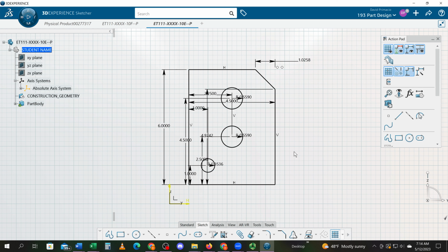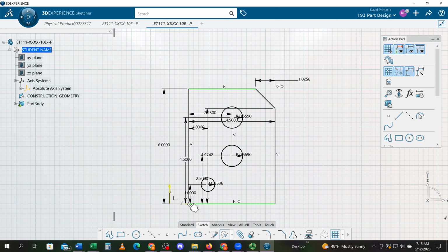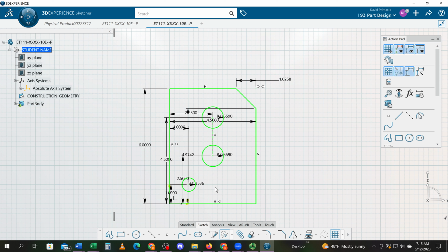And then I'm going to, don't change the dimension, don't move nothing, just go right to contact, and if you can, try and double click it so you can contact this horizontal line to this yellow vertical line. And then see how it's still highlighted? I can go from this vertical line here to this axis. And then when I open this up in the sketch, it gave me two coincidences.